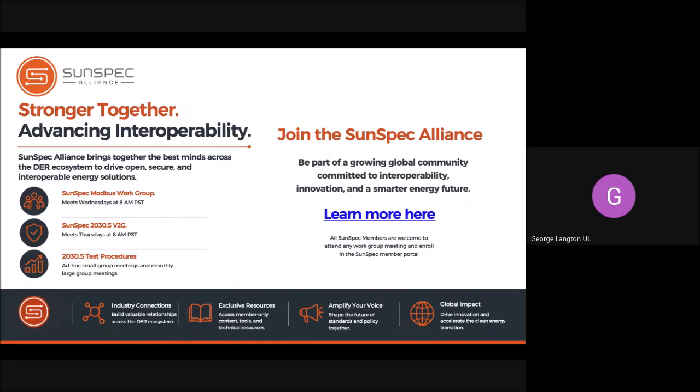Okay, because they are not KVAR oriented as a synchronous system is, they have to create their own concept of synchronous. That would be through the kilowatts and the amount of amperage shared proportionally between the systems. This is all reality. This isn't theoretical. Right. But we're getting into the weeds.